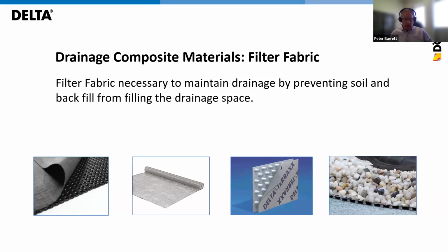Consider quality. These fabrics can be attached by either being heat welded, glued or bonded, or even loose laid. If they're not fixed on every dimple, that fabric can stretch under load, impinging on the space between the dimples, thereby becoming less effective. It has been shown that those that are attached at every dimple will have better performance at resisting soil pressure.